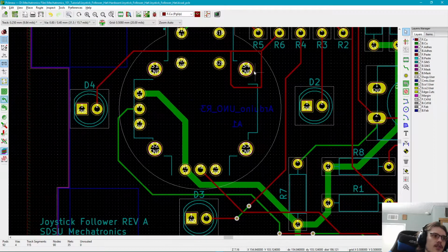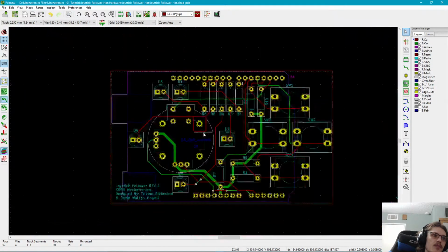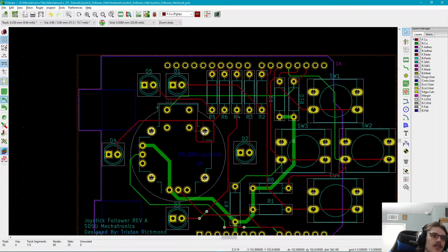Of course, since these vias attach to the top and the bottom, it's attached to the bottom ground plane, but not the top, because the ground plane poured everywhere else but here. And that's a problem.